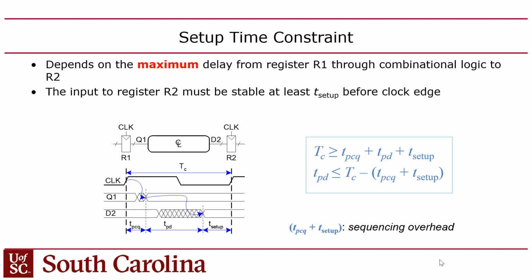But in this class, if we had a lab where we tried to get your CPU to run at, say, 200 megahertz instead of 50. Let's overclock the snot out of that thing. Well, you can do that, except you may have to deepen the pipeline, because the way the pipeline is set up now, we have that long propagation delay in the execute stage. But anyway, you guys with me on this?